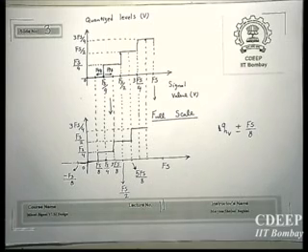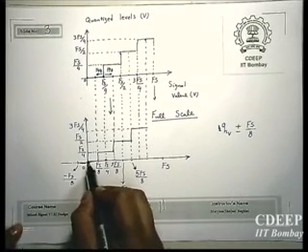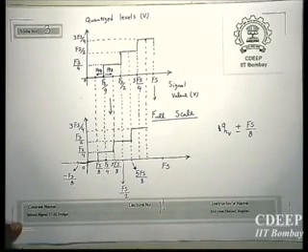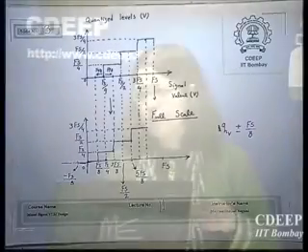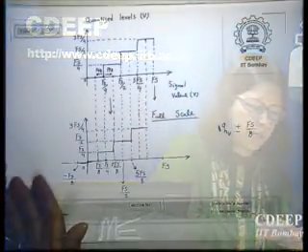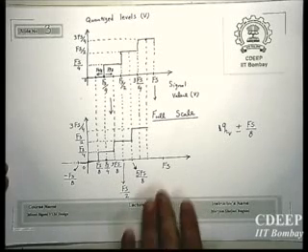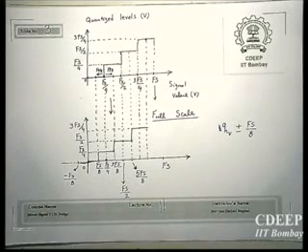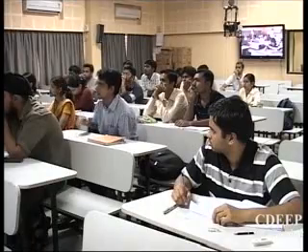Here, only for the range around 0, you will not have it. The reason is that practically we consider my signal to be between 0 and Fs. But if my signal is not between 0 and Fs, suppose I have a fully differential signal which can take negative values, then I will go from minus Fs to plus Fs, and I can cover this perfectly. For differential, this is preferable.